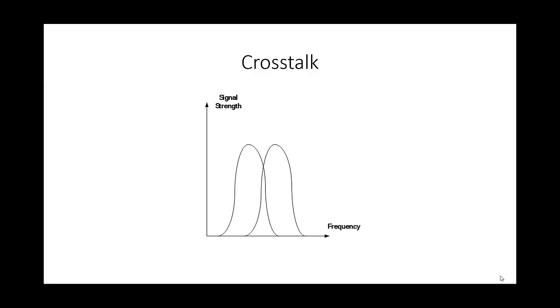Finally, we're looking at MIMO, which stands for Multiple Input, Multiple Output. All of the systems described so far can use wireless network adapters with a single antenna for sending and receiving signals. These are referred to as SISO, which stands for Single Input, Single Output devices. MIMO is a technique used to enhance OFDM transmissions by using multiple antennas to transmit and receive signals. This increases the overall speed of data transmission.